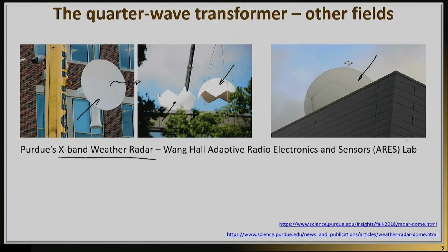but unfortunately you will create some reflections, because as the incident wave is hitting the radome, it's going to find some obstacle and a lot of it will be reflected back. And that's certainly not desirable at all, because the antenna typically radiates significant power, and you don't want a lot of power to hit the antenna back for a variety of reasons.